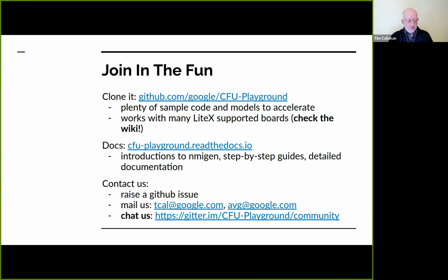We actually have just recently made it so that we pull the current version of TF Lite Micro every night. So we are always on the head of master. Now, this does pose a potential risk. We're counting on the APIs not changing too much. And fortunately, TF Lite Micro is set up pretty well at the kernel boundary that the subroutine interface likely won't change, even if some internals change.